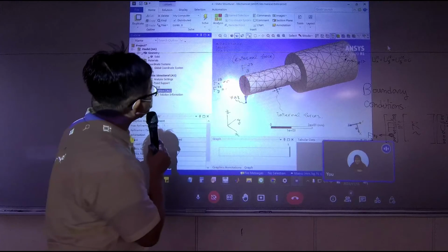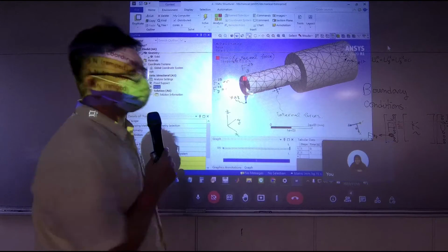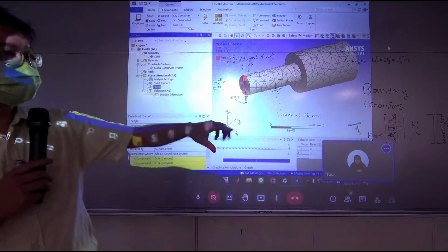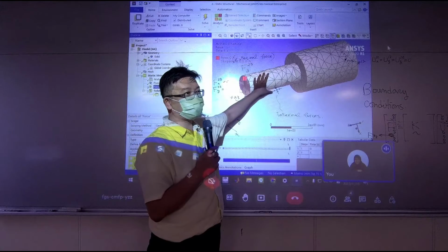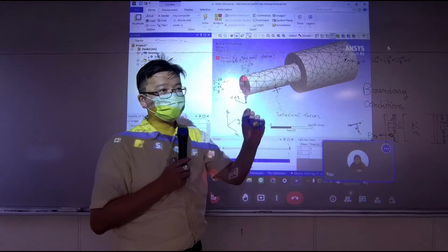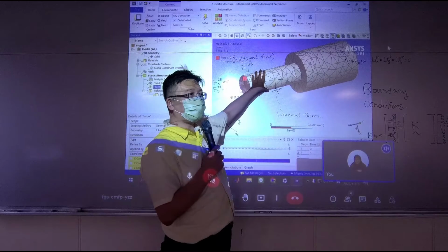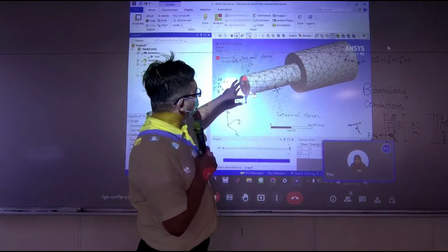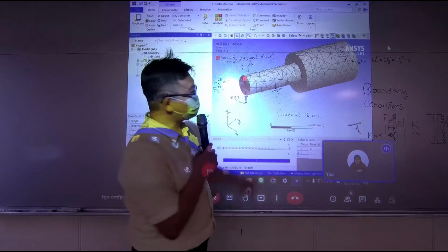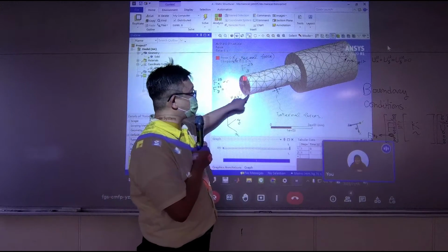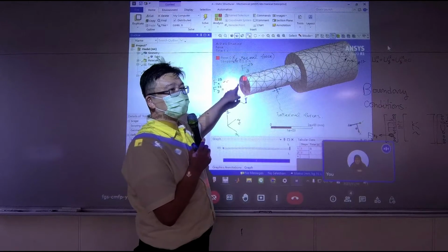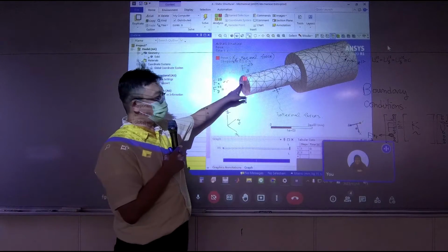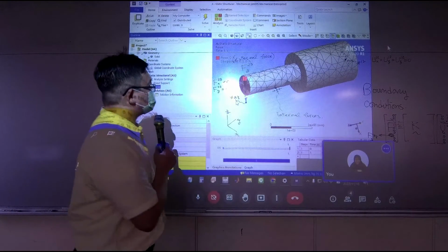Is it on the surface or on the node? On the surface. So if you want to assign a force on the node, you need to let the computer find the node. But in his geometry, there's no point right there, no point object. So for easier demonstration, today he applied the force onto the entire surface. So in this case, this is a shear force applied to the entire edge. Okay, so try to solve it.